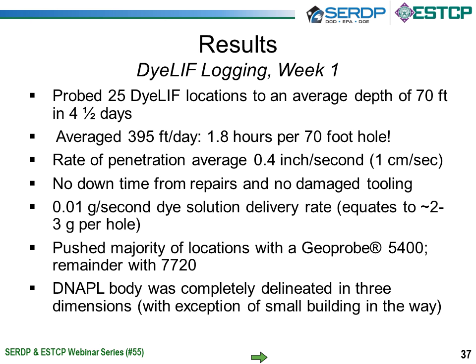And the results after 1 week, and not even a full week, but just 4.5 days of work at this site, we probed 25 different locations, and to an average depth of about 70 feet. We averaged 390 feet a day, so a 70-foot hole could be completely explored or probed in less than 2 hours. Our rate of penetration averaged about ½ an inch per second.